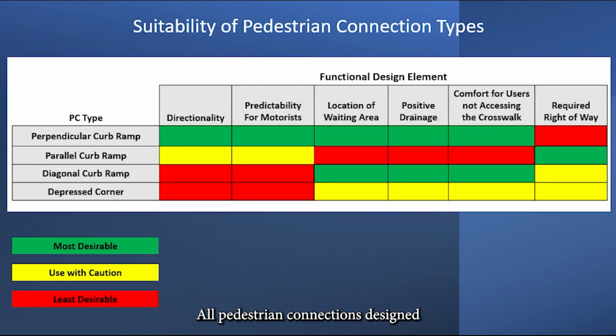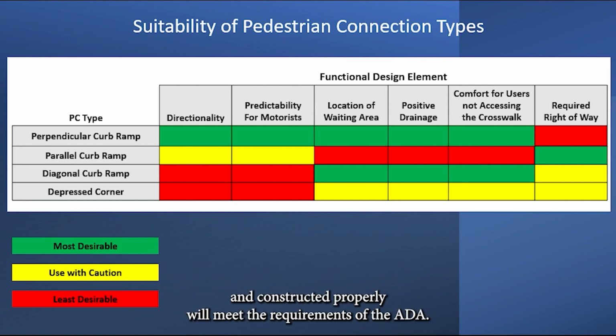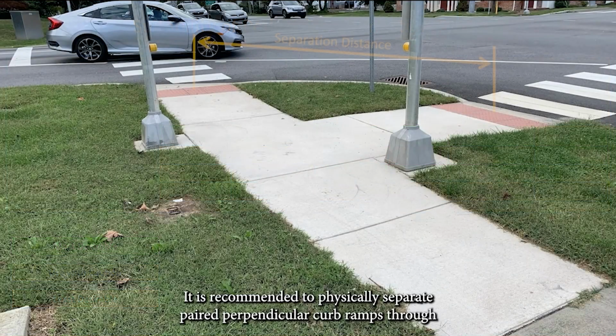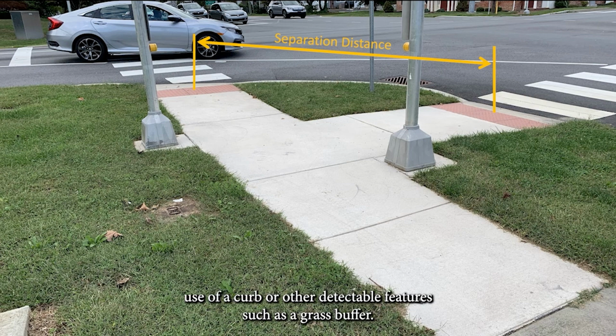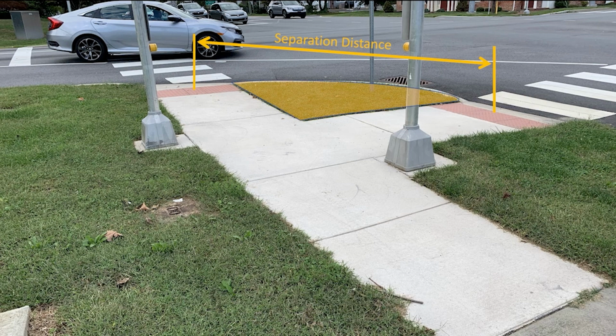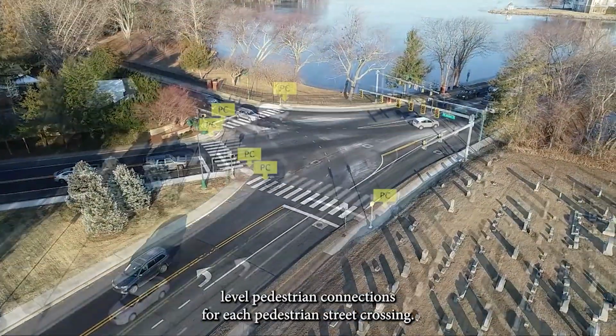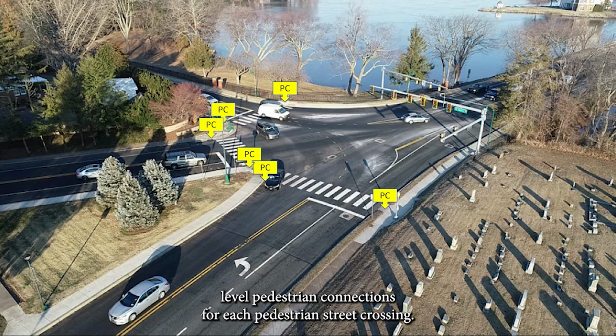All pedestrian connections, designed and constructed properly, will meet the requirements of the ADA. However, some layouts provide more desirable characteristics than others. All proposed locations should be analyzed individually to determine which pedestrian connection type is most suitable. It is recommended to physically separate paired perpendicular curb ramps through use of a curb or other detectable features, such as a grass buffer. The department's preference is to always provide separate street-level pedestrian connections for each pedestrian street crossing.